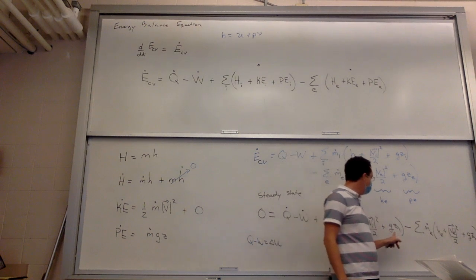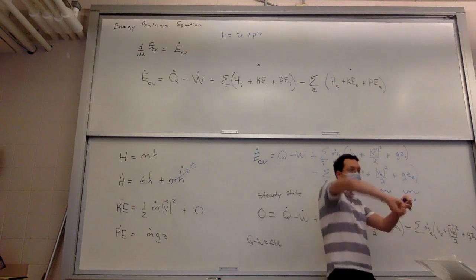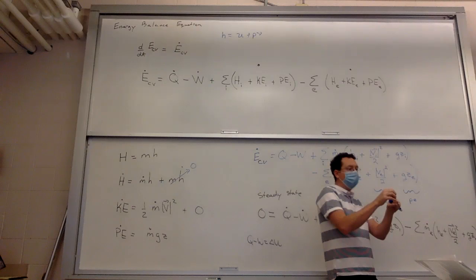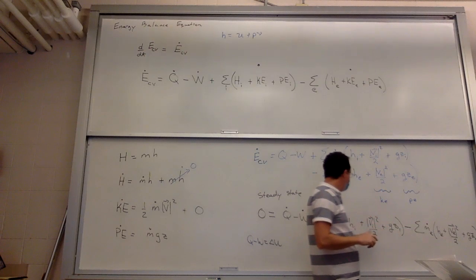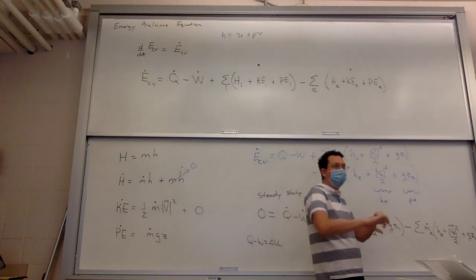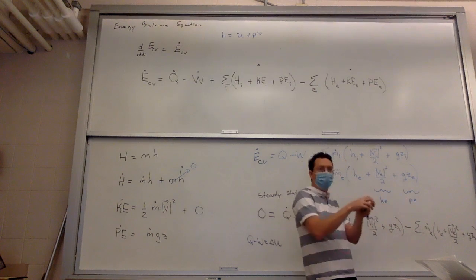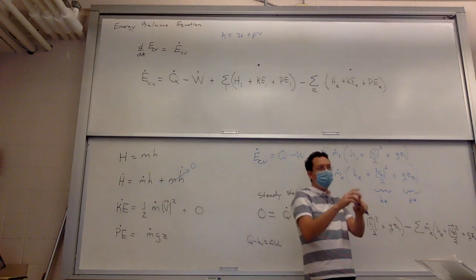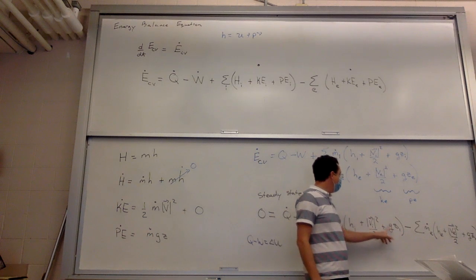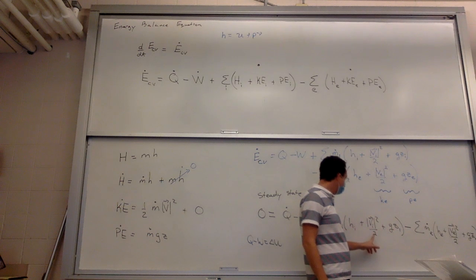And then also, if you have a bend, you get extra contributions to the loss, not just the overall pipe. For each bend, it depends on the angle and the shape of the bend. I think it's also a velocity squared term.